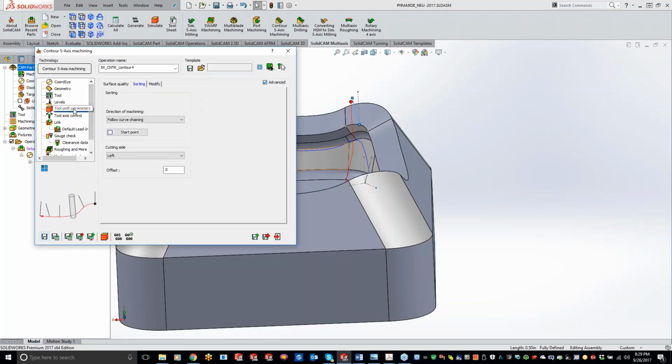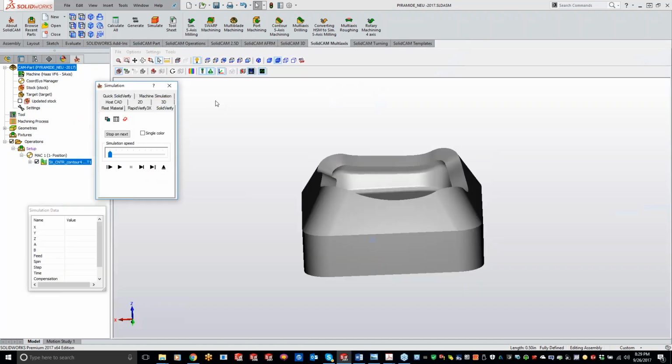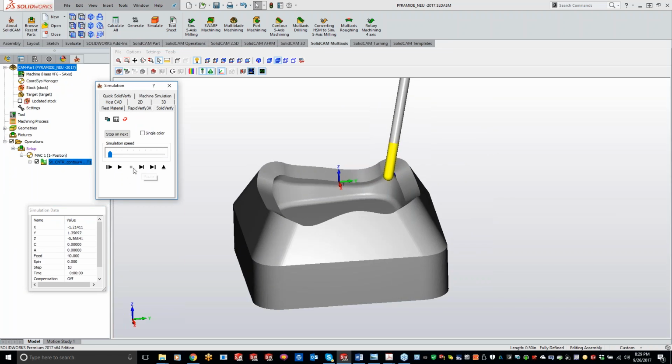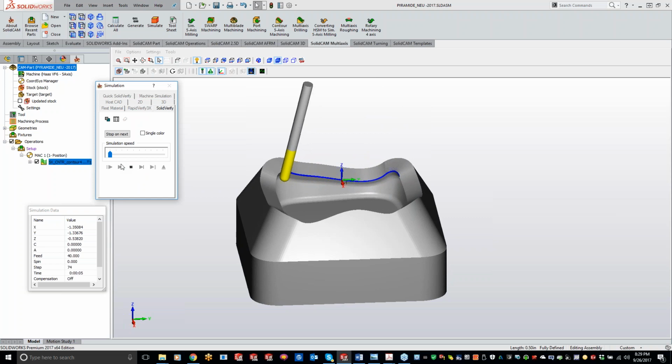Like I was saying before, we go to our toolpath parameters here, and let's just put a 15 thou negative offset in there. And now we should have a nice chamfer going all the way around the inside of the part there.